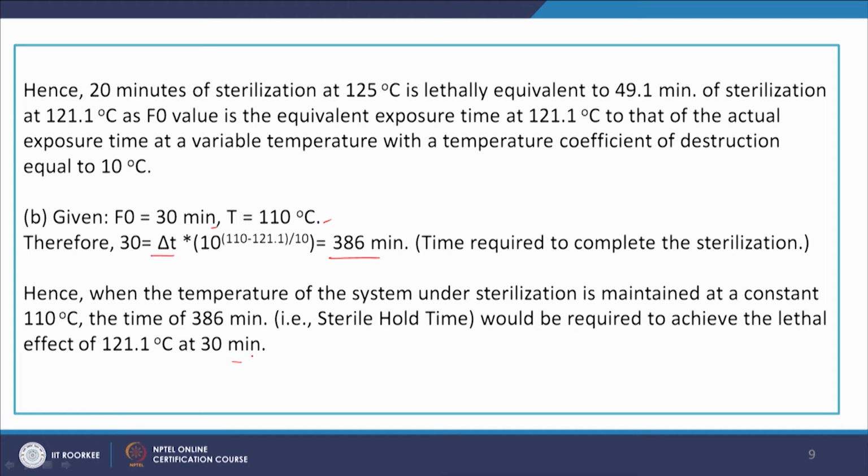So, it is very clear from this data that if the sterilization temperature is lower than 121 degree centigrade, very prolonged heating is required. So, that is not feasible. So, normally the temperature is maintained at 121 degree centigrade and more than that.